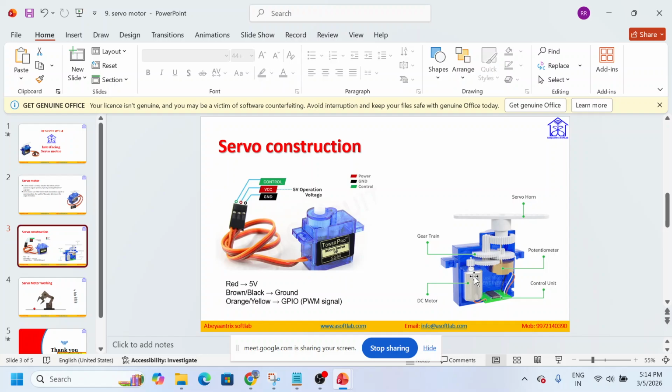Okay, which is used to control the direction and speed of the DC motor, because there will be a huge back current, back EMF, generated when you run the motors. In motors there is mechanical movement, and the back EMF generated from that motor will affect the controller. To avoid this, we use a motor driver for the larger capacity motors. The next motor driver we will use is called the L293D IC, and we will use that to control the DC motor.